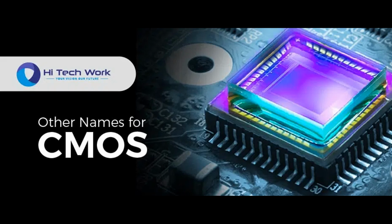Complementary Metal-Oxide-Semiconductor (CMOS) technology utilizes both N-type MOSFETs, NMOS, and P-type MOSFETs, PMOS, in a complementary manner to implement various logic gates and circuits. Here's how CMOS logic gates and circuits are constructed. Basic CMOS inverter. The most fundamental CMOS circuit is the inverter, which performs the logical NOT operation. It consists of both NMOS and PMOS transistors connected in series between the power supply, VDD, and ground, GND, with the output taken from the junction between the transistors.